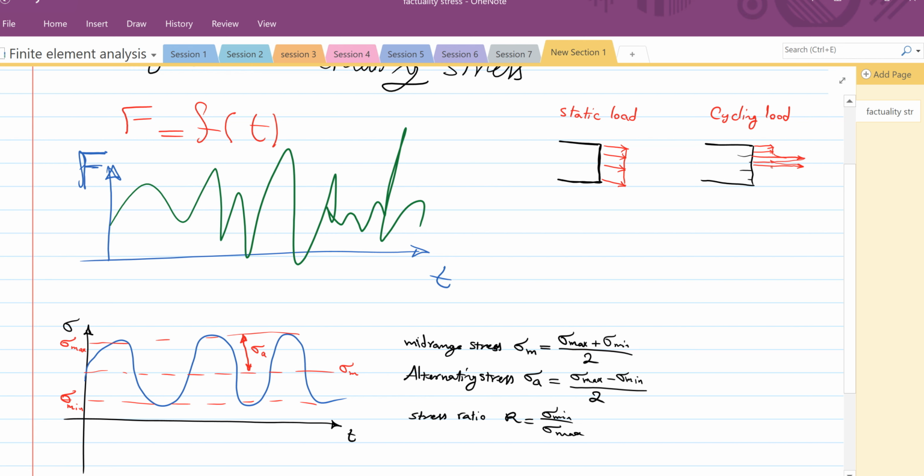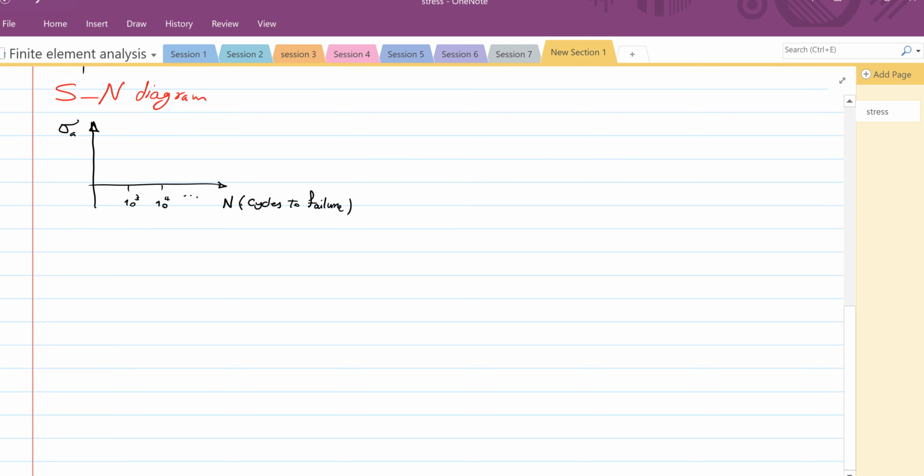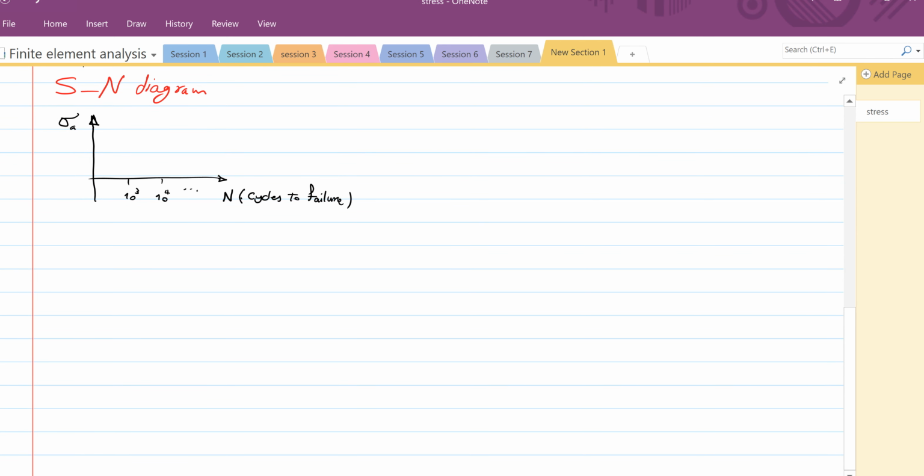Then again uniform, another crack, very high stress. So as you can see, close to one of those cracks, we could reach that ultimate or yield stress, and our system is going to fail. So that is why it is important that we consider the number of cycles to reach that failure and prevent that crack propagation.